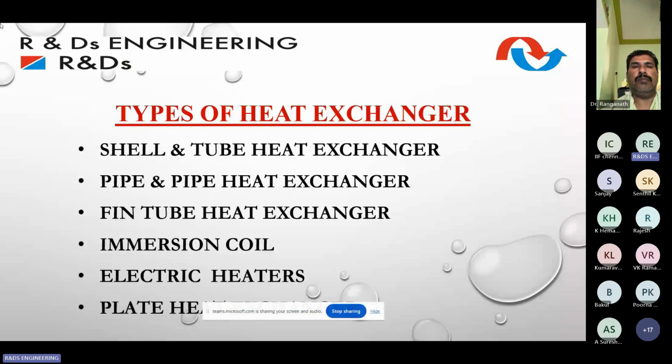There are some applications like anodizing plant, phosphating plant, where, to maintain the temperature inside the tank and attain the quality, they circulate chilled water inside that coil. So this coil is generally placed inside the tank. This type of heat exchanger is also available in the market.